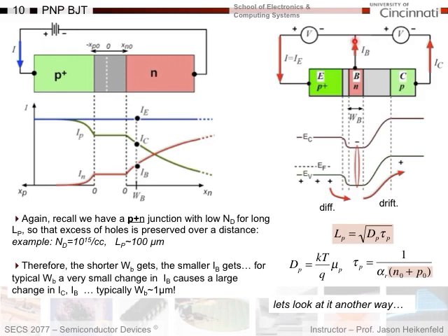You can kind of look at this in terms of the doping levels. Again, it's P plus N for the junction, and you have low N-type doping here in the N-type material. Let's say, for example, that it's 10 to the 15th per cc for the electron doping. You could calculate, using the equations we know, that the diffusion length for holes would be about 100 microns. Remember, diffusion length was sort of the average distance a hole would go in a material before it recombines.